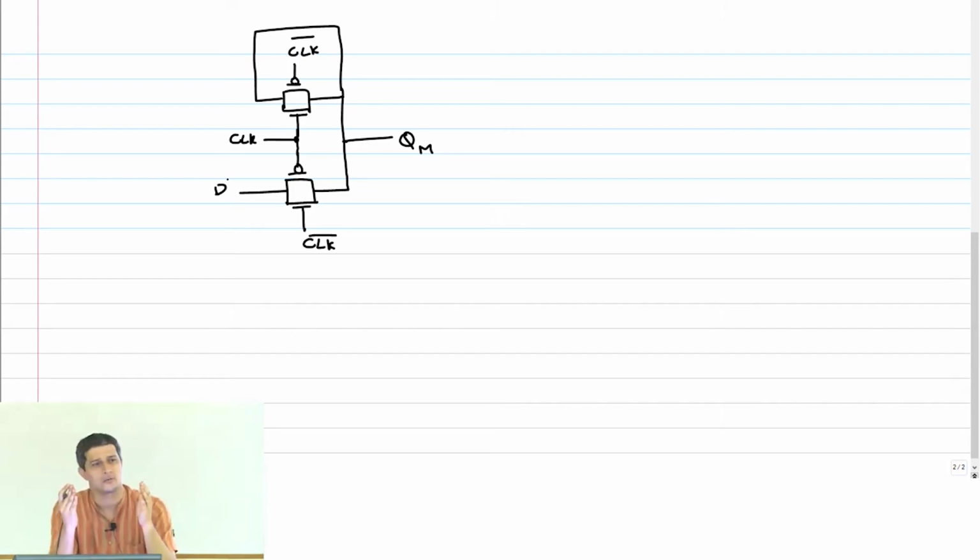What does characterization mean? It means that as a standard cell designer, I design a gate or a flop, and then in your assignment now, you are characterizing the delay of an adder against the loads, against the slew. What are you doing? You're basically saying if the load is this much and the delay is this number, I should be able to give you that number. That is what is known as characterization, right?